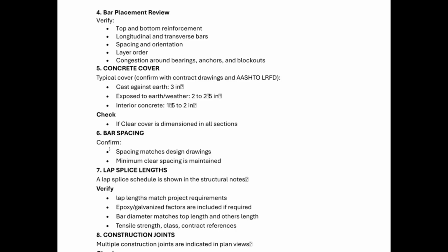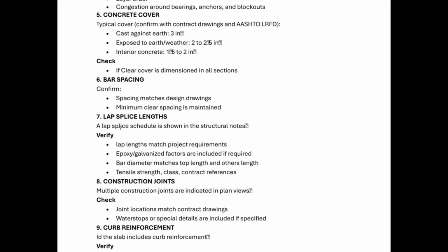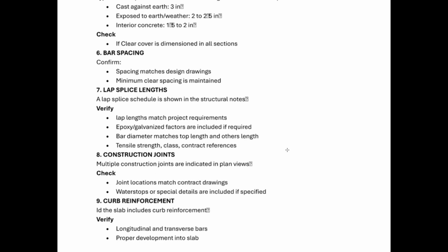Bar spacing. You need to confirm the spacing matches the design drawings and the minimum clear spacing is maintained. Number 7, lap splice length. A lap splice schedule is shown in the structural notes. Verify the lap length matches project requirements. Epoxy or galvanized factors are included if required. Bar diameter matches top length and other lengths. Tensile strength, class, and contract drawing references.